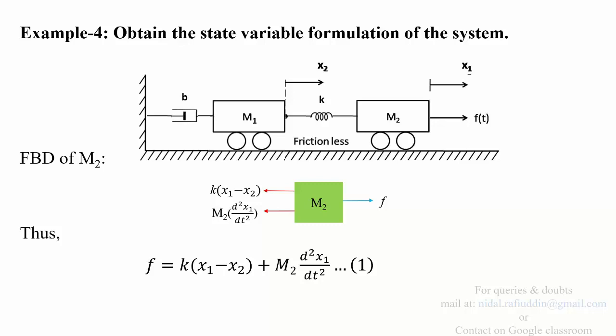But for mechanical systems, as I told you yesterday, whenever you deal with mechanical masses, for any mass you will be assuming 2 state variables. One is displacement x, the other is velocity. Which means that in this particular example, you will have displacement x1 for mass M2 and displacement x2 for mass M1. In fact, this should have been written like x2 here and x1 here, but nevertheless.